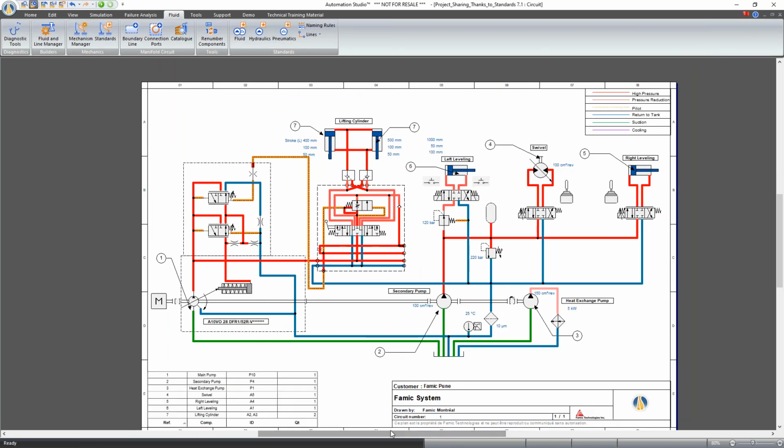Okay, so still some time. Are there any other questions, Bruno, Dennis? Yes, go ahead, Dennis. There was a question about this type of appearance. David asked if he wants to have two colors for two reduction valve levels of lines. So you answer the question: you have to create two functions, reduction one and reduction two, and an appearance for reduction one and for reduction two, and assign them to the installation circuit.